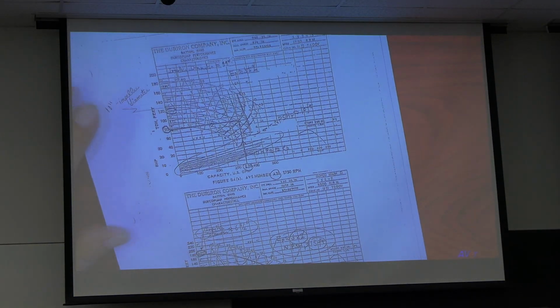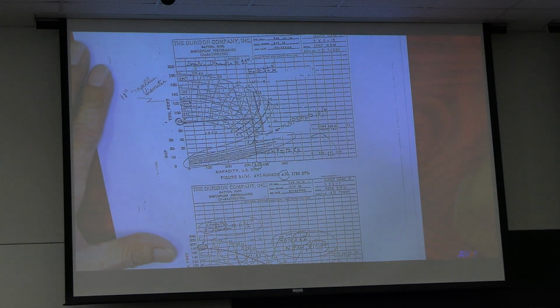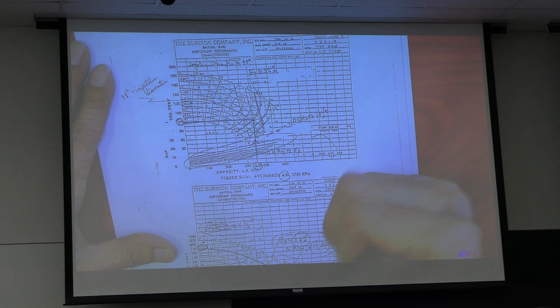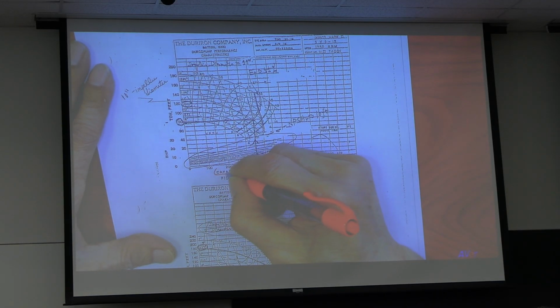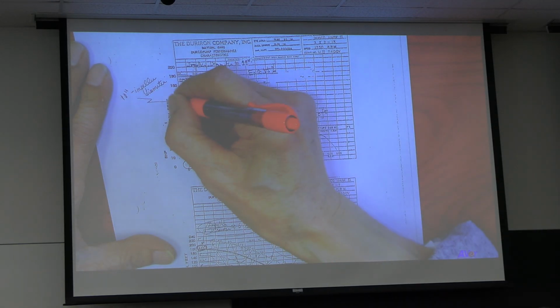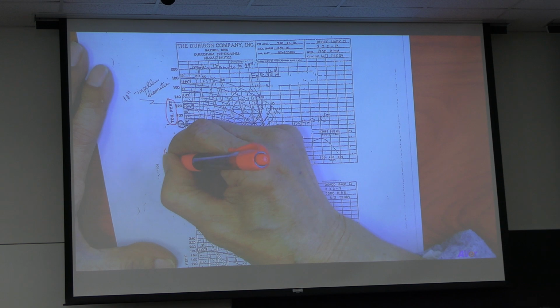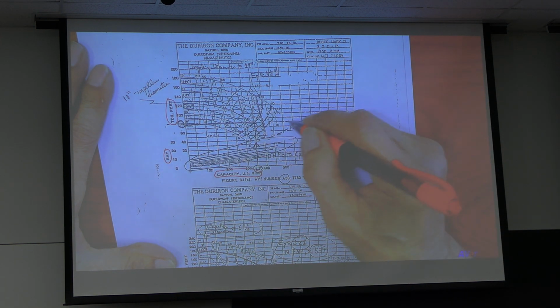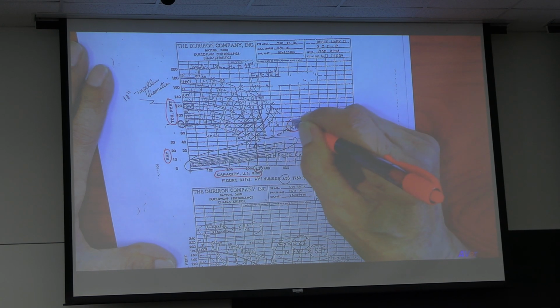Our goal is the following. Look at the pump curve. Understand capacity, total dynamic head, brake horsepower, net positive suction head available.